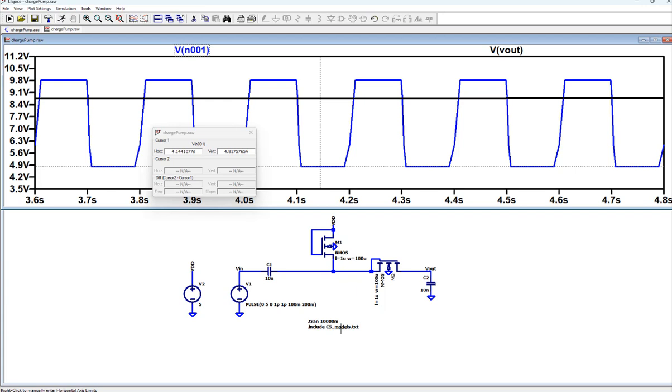But the thing is, C5's threshold voltage is not 0.2. It's 0.5 or 0.6, I think. On ours, I think it says... Oh, yours is 0.2. Yeah. So yours is different. Yours is a 50 nanometer technology, not this one. It's a different technology. Yeah, I think it's 50 nano, right? It has 1 volt as VDD, right? So it's a different technology. In that case, you need to use these numbers instead of the 5 volt ones. I'm sorry, it's a little bit confusing. So it's a different VDD and different threshold voltage.